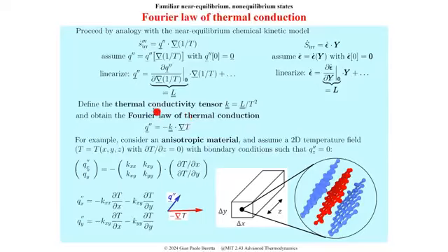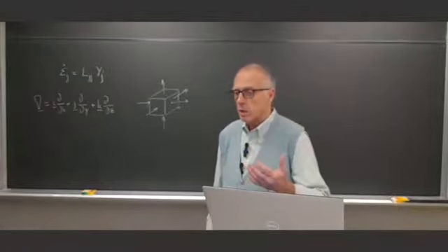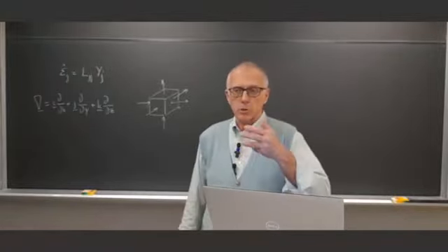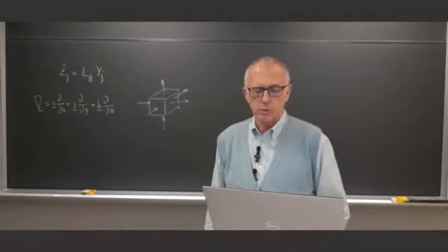On which most of heat transfer is based. So this is a fundamental step. Then from this you construct all the applications. Notice that K is a tensor, first of all, and only in some special cases is that tensor isotropic, so you need only one variable to represent it.